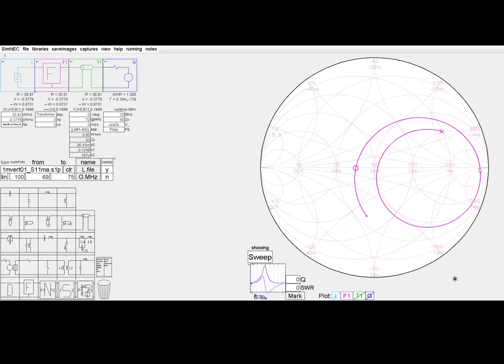The second resonance is up here, that's the high impedance or the parallel resonance, and the next series resonance is where the antenna is 3/4 wave in length, and that's down here. So that's interesting. Let's just insert a little bit of transmission line and look at what the effect is on that pattern. I'll just insert a very small amount, so 100 millimeters.